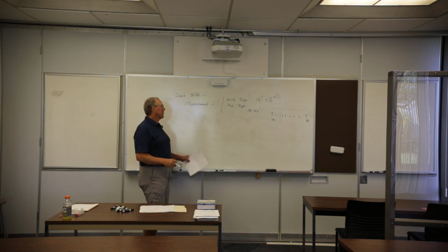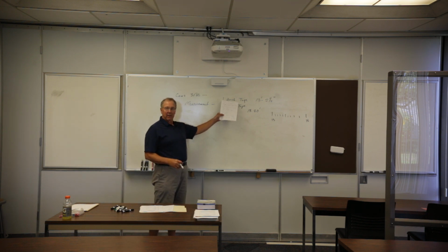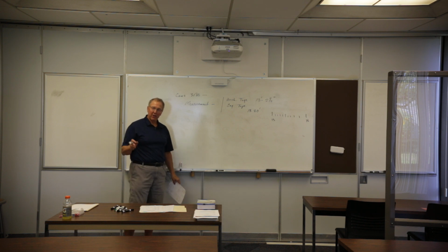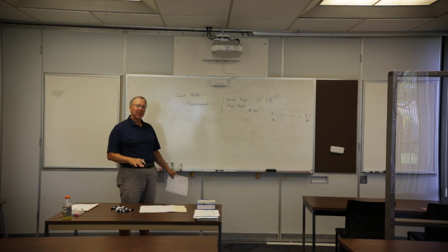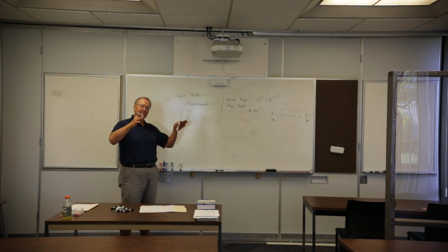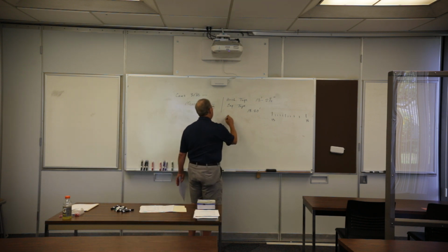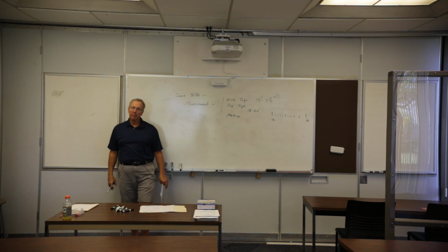Every drawing I've ever seen that's associated with architecture has these dimensions on it. Every print I've seen associated with civil work, site work, land, roads, anything associated with site work has an engineer's tape on it. So you're going to have to go back and forth between the two tapes. The site plan is going to be in feet, tenths, and hundredths. The building sitting on the site is going to be in feet, inches, and fractions. And then, if you work abroad, you're going to have a metric tape.